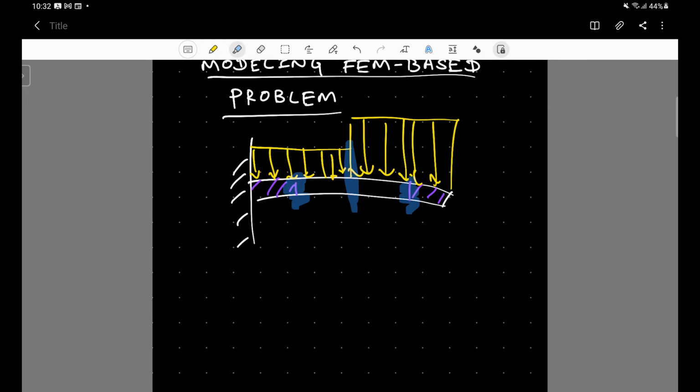This is a bending problem, and in order to accurately describe a bending problem, you need to use linear strain triangular elements. If you are using constant strain triangular elements, there can be deviations, but if you drastically increase the mesh size, you might be able to at least get close to the results obtained by linear strain triangular elements. So there should be a feeling for this. It should be at your fingertips, they say, when you come to model such a problem.